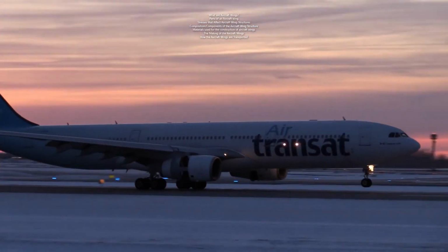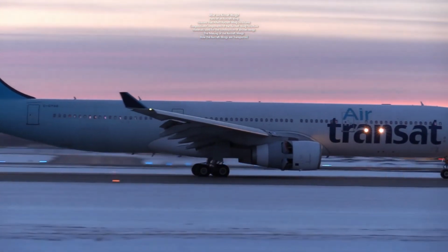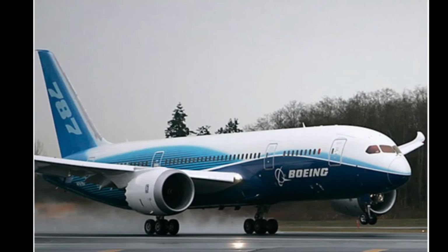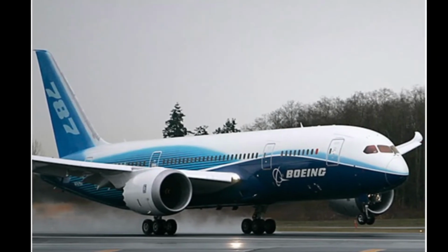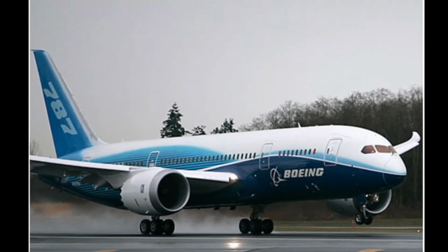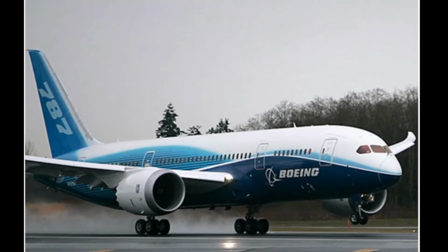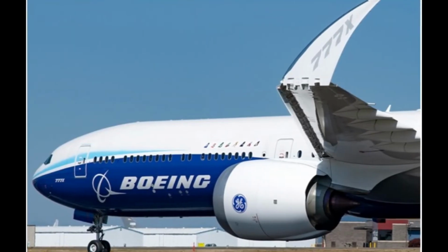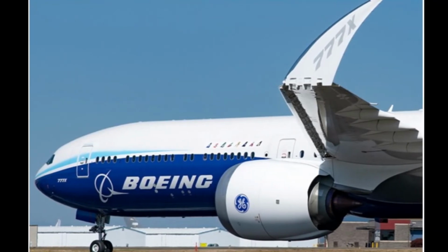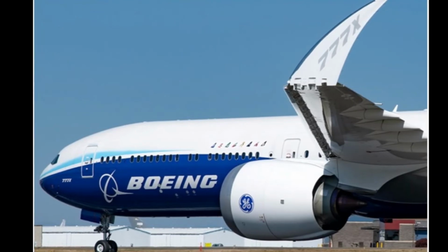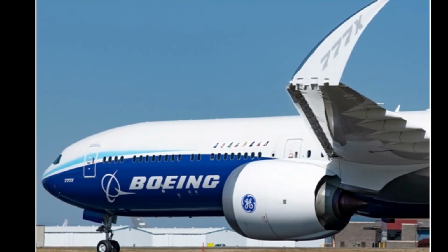Aside from these main elements, there are longitudinal stringers and bulkheads in the structure. The stringers run spanwise like the spars and increase the buckling stress of the skin even more. The bulkheads run chordwise and help to redistribute the loads around the structure. The arrangement of the wing structure ensures the wing is sufficiently rigid, but still with a little flex. This flex allows the wing to suppress the gusts of wind and sudden changes in aerodynamic loads that might occur during flight, allowing for a smoother flight.